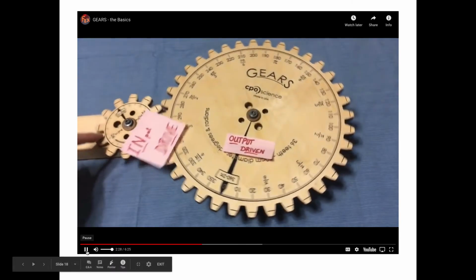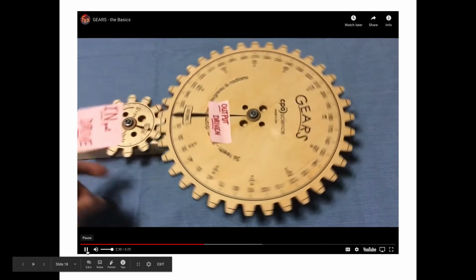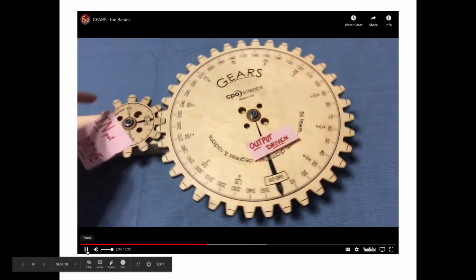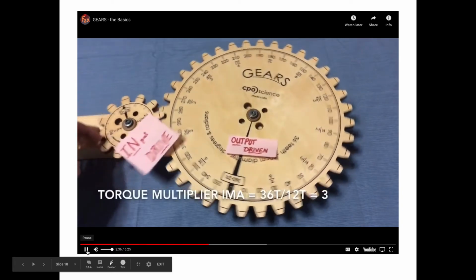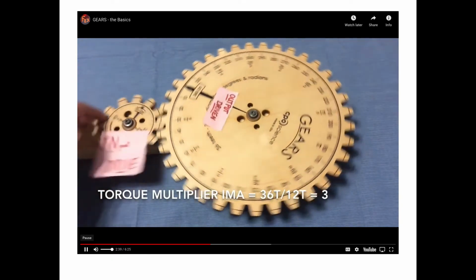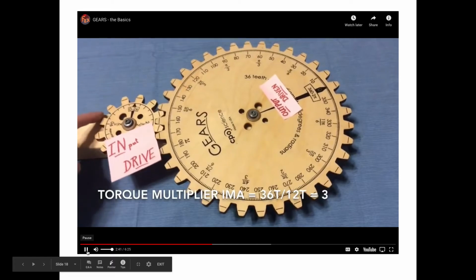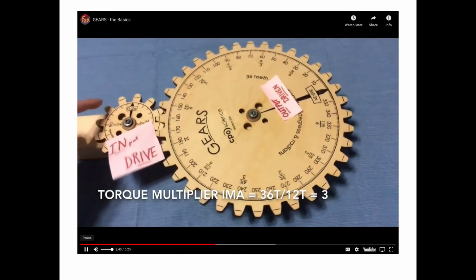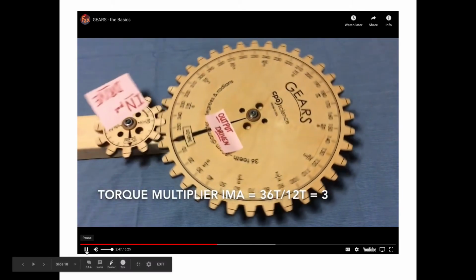Now we're back to that 36-12 combination. Switch the input and the output, and you now have a torque multiplier. Clearly a speed divider identified visually, so it is a torque multiplier of 3. The mechanical advantage is 3. Note that a counterclockwise input gives you a clockwise output.